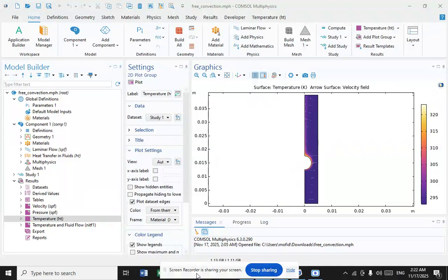A flow in a narrow slot between parallel vertical plates is formed in the form of periodic circulations. In a horizontal fluid layer between cooled upper and hot lower walls, the fluid flow has a cellular form with hexagonal cells, in the center of which fluid ascends from the hot surface to the cold one, whereas in the periphery it descends.